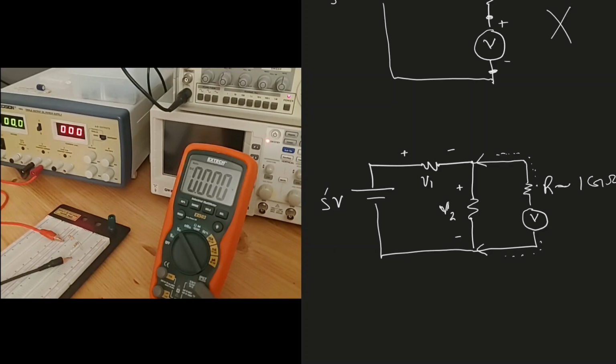Okay, so it's a very large resistance and it is approximately equal to an open circuit. Okay, so we can think of it as an open circuit or infinite resistance. So therefore, it will not change the voltage V2 in the circuit. And now it will be able to measure, because the voltmeter now knows how much voltage we have here and how much voltage we have here.